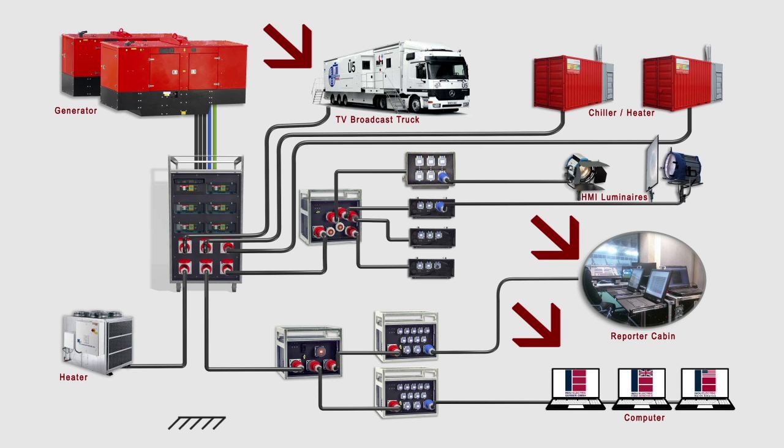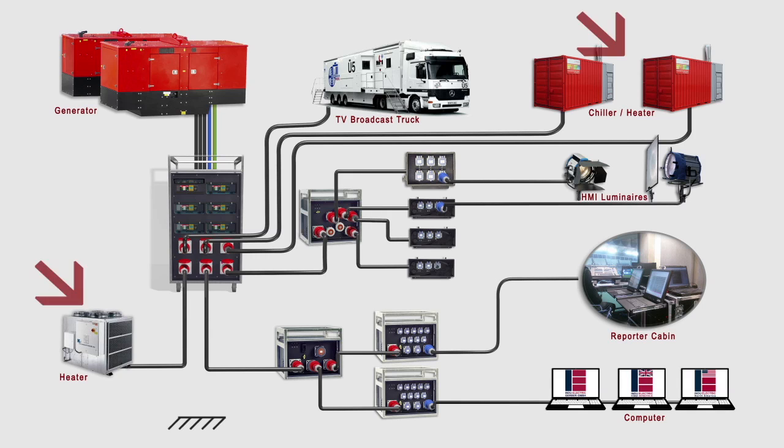Chargers for laptops or mobile phones are a great example to illustrate normal leakage current. Up to 4 mA leakage current may occur depending on the manufacturer of the charger. Dynamic leakage current. Dynamic leakage currents occur, in particular, when switching devices with interference suppression filters. They generally have a duration of a few micro or milliseconds and can have a magnitude of several amperes.